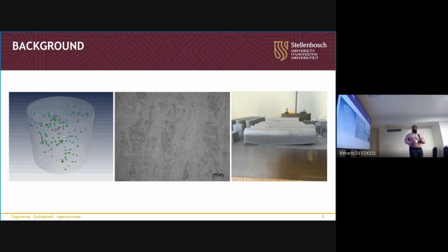What typically occurs is we end up getting some type of porosity in it. We have certain types of microstructure, in this case with titanium Ti-6Al-4V. We get the martensitic microstructure. You can see the alpha prime or the martensite, these black needle-like structures, where we have it in a prior beta columnar structure. So the build direction was up, and you can see this columnar-like structure going upwards.